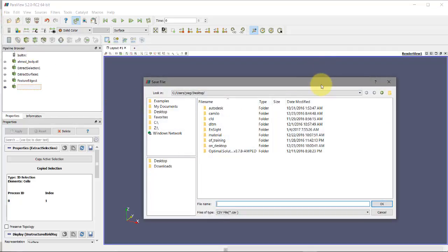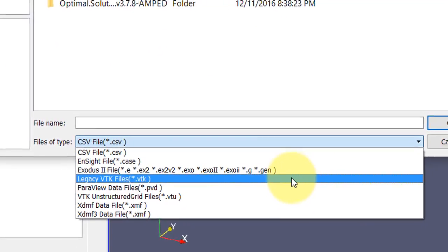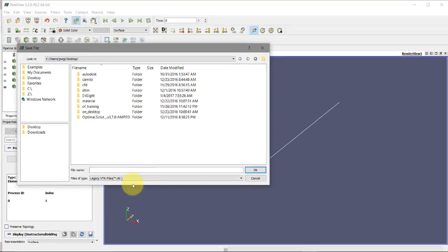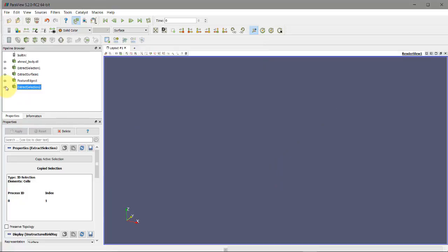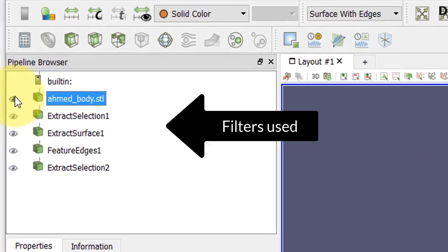Now be careful, because for lines in OpenFOAM or snappyHexMesh, you need to save it in VTK format. So you save that line as VTK, then there is another utility in OpenFOAM, I will show you later how to convert it to the format that OpenFOAM will recognize to apply a different refinement there. As you see, contrary to what you think, you have a lot of control. It can be a little bit tedious, but you have all those visual references here, so you can rely on Onshape, create your domain or those boxes, get coordinates for blockMesh, and then come to Paraview.